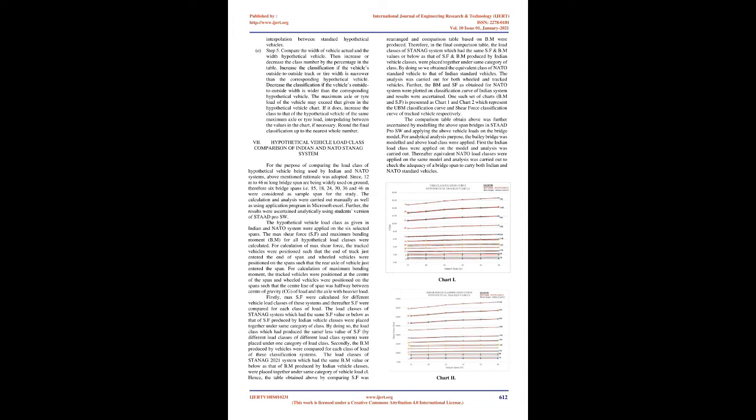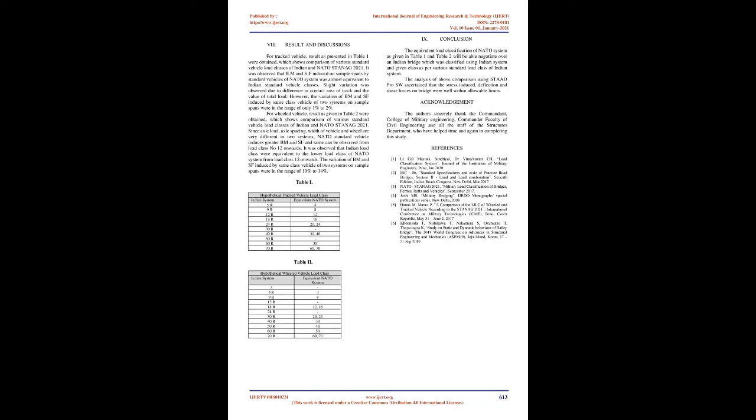For calculation of maximum shear force, the tracked vehicles were positioned such that the end of the track just entered the end of the span, and wheeled vehicles were positioned on the span such that the rear axle of the vehicle just entered the span. For calculation of maximum bending moment, the tracked vehicles were positioned at the center of the span, and wheeled vehicles were positioned on the span such that the center line of the span was halfway between the center of gravity, CG, of the load and the axle with the heavier load.